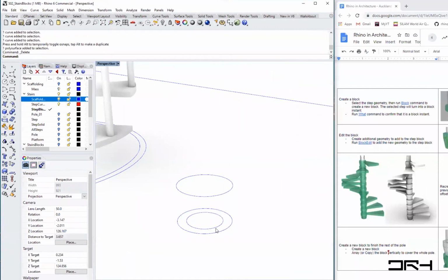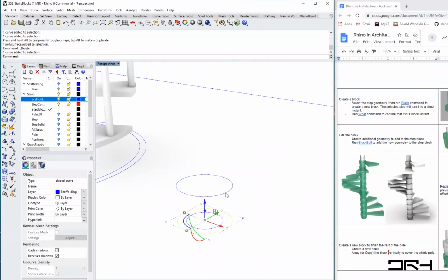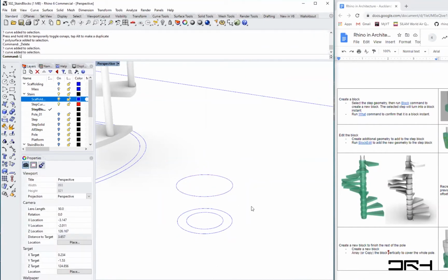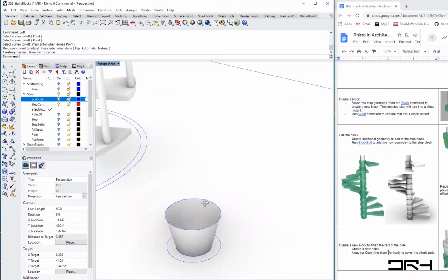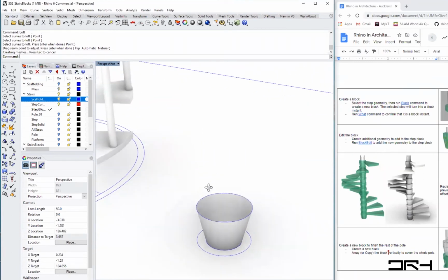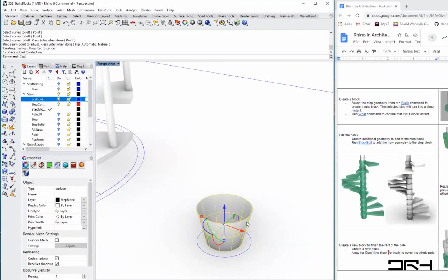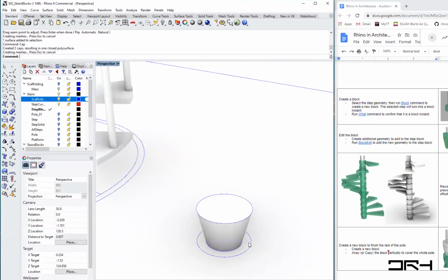I had these two initially, so I created a copy all the way up here and used the Loft command to loft between this and that, and pressed Enter. And that created the lofted surface, but you see it's just a thin, hollow surface. You can use the Cap command to cap it, and that makes it more solid. One of the other things I should have done is, I have the pole, which is the cylinder. If you recall, let me just remove the intersection and the near.